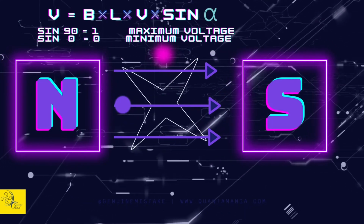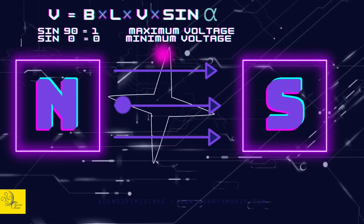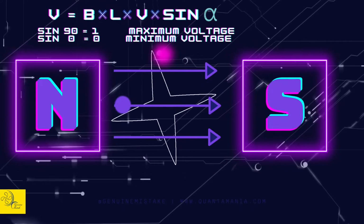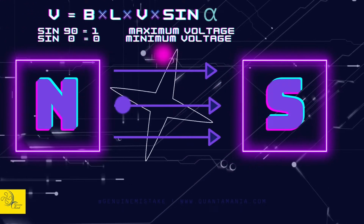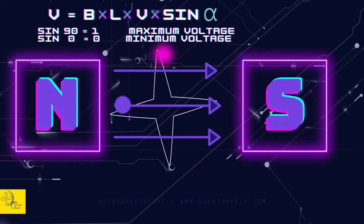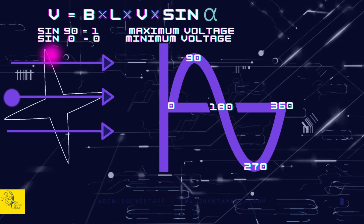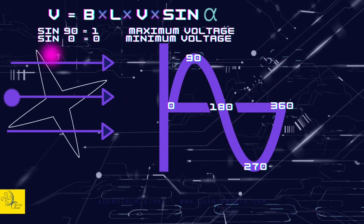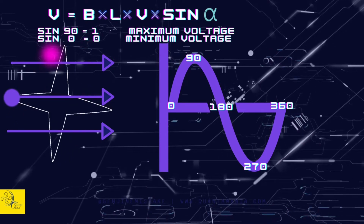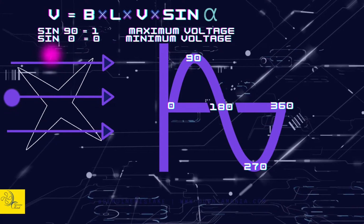Well, to bring the factor of alpha in the formula, we need to know the sine of alpha. Because as we know, the sine of 90 is 1, and that's why at 90 degrees we will make the maximum voltage, and at 0 degrees, because the sine of 0 is 0, then we will make minimum voltage or 0 voltage.